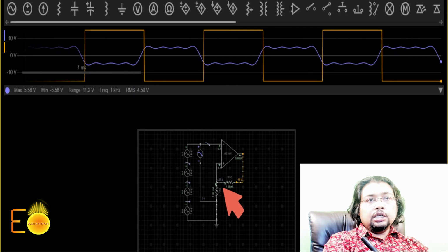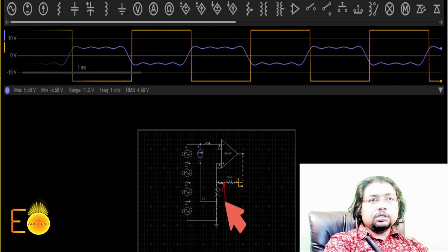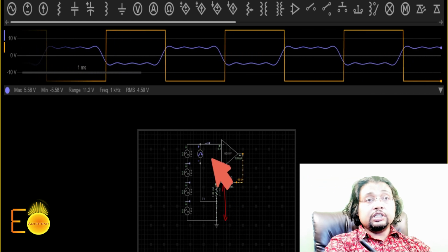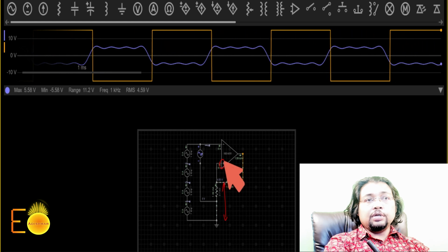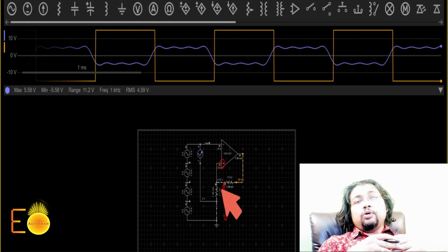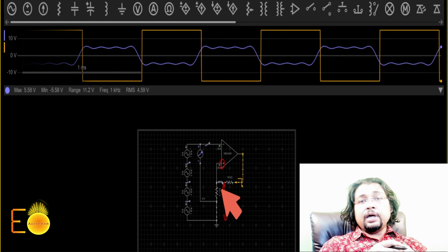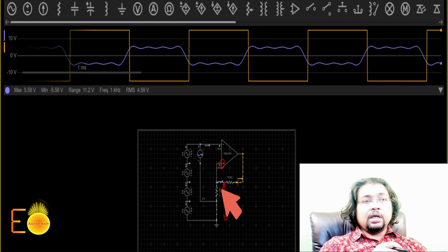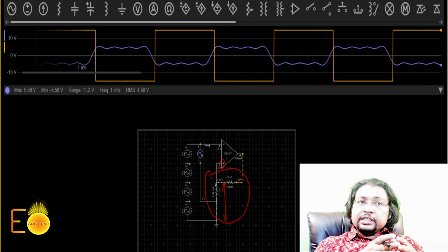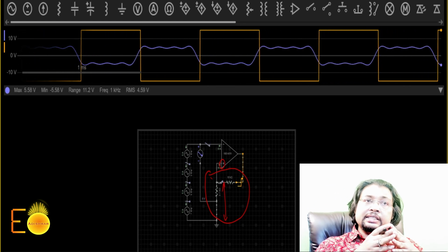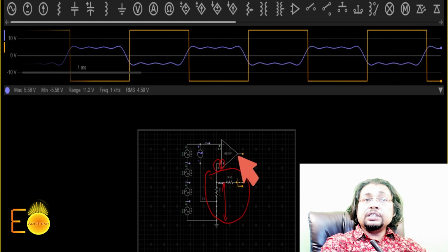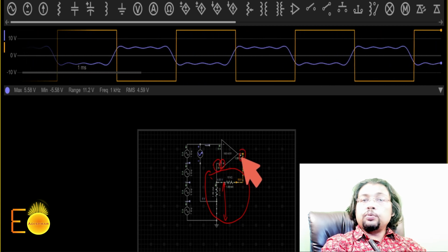As a result, the potential across this resistor appears as the reference voltage at its plus terminal. Such a configuration provides positive feedback to this operational amplifier, which increases its gain further. The advantage of such a positive feedback is that in this case, we are going to get the reference voltage depending upon the output voltage.